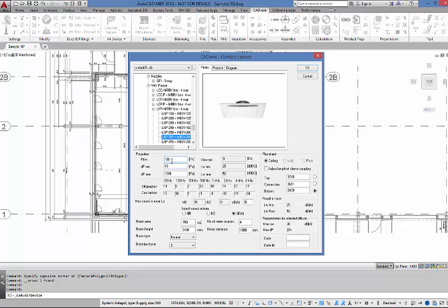Now we know this device has a range between 40 and 1216 Pascal. That's a balancing area. That's strange. But this will create between 28 and 53 decibels in sound power. 53 is definitely too much. So if I have a room where I allow not more than 35 decibels, and I can create the room here in a quite easy way, then we can see immediately that we can still use a damper up to 274 Pascal to not overload the room with too high sound levels. So all of this will be taken into account in the calculations of CADvent.